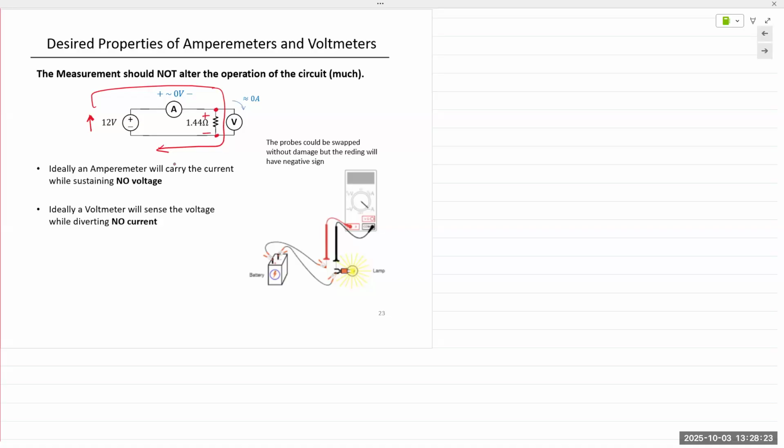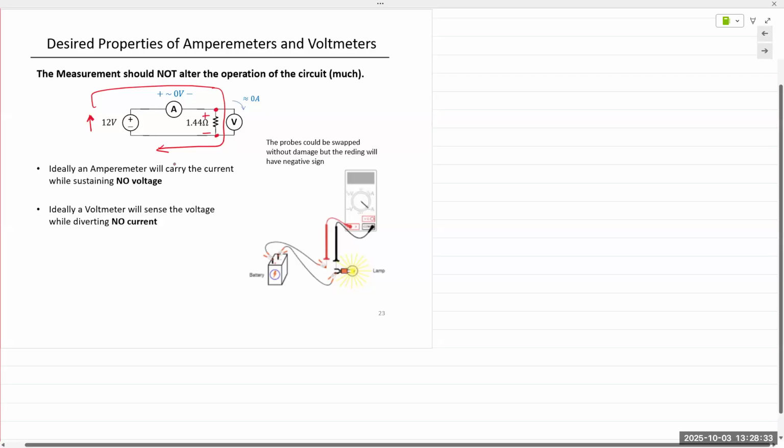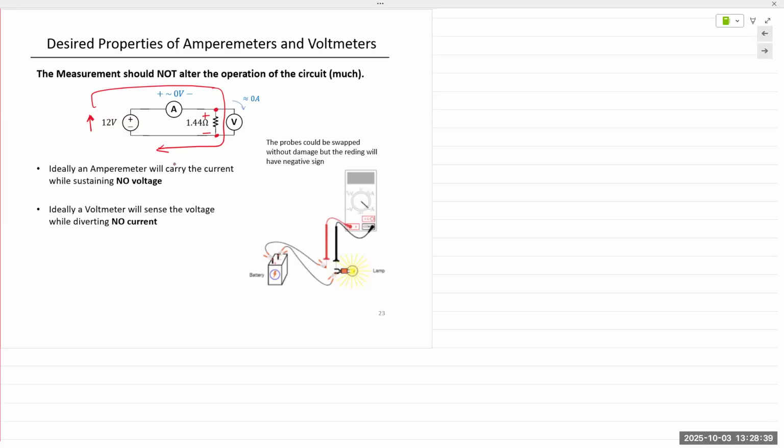Before we perform a measurement, we do need to visualize, or at least understand, the circuit and understand where the polarity is positive and where it's negative. And so we connect a meter according to that observation. So if you take the positive terminal of the meter and connect it to the top end and the negative to the bottom end, we would end up with a positive voltage.